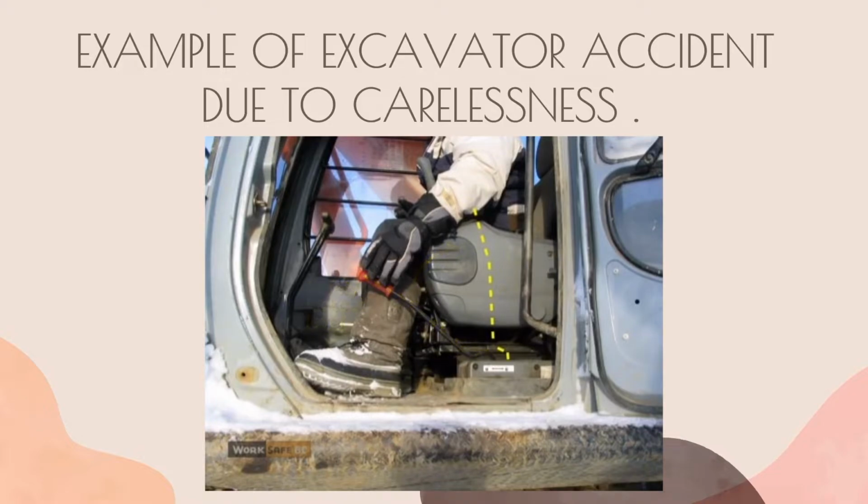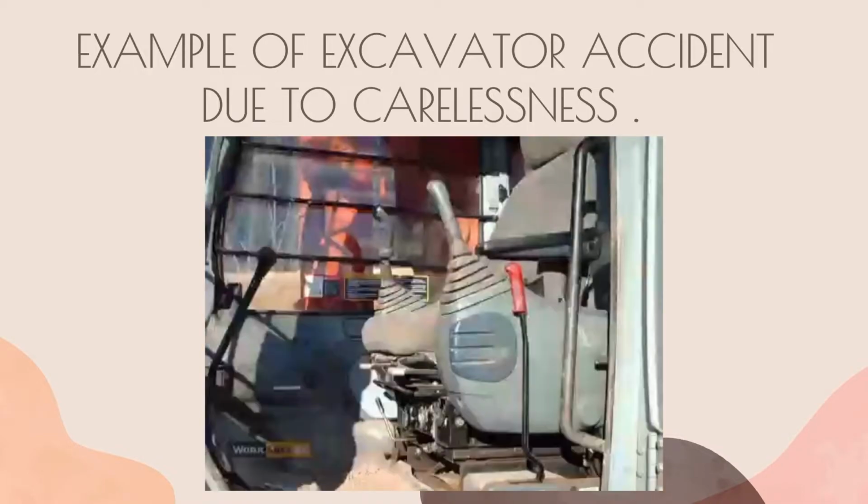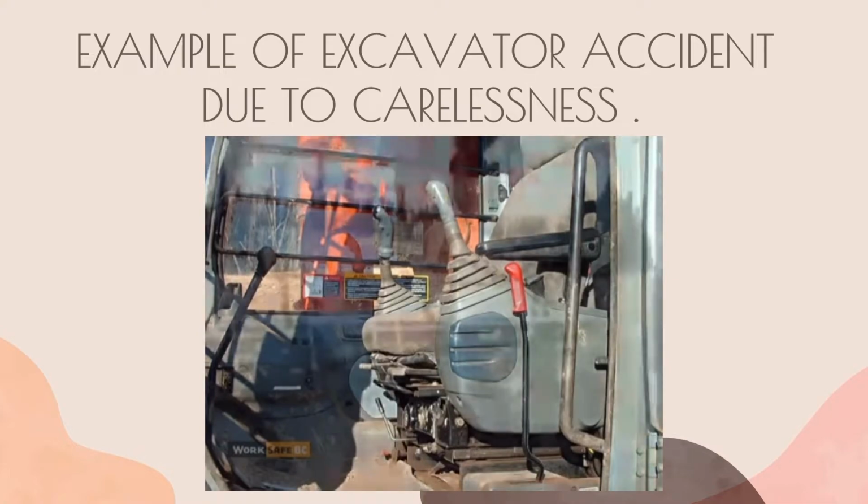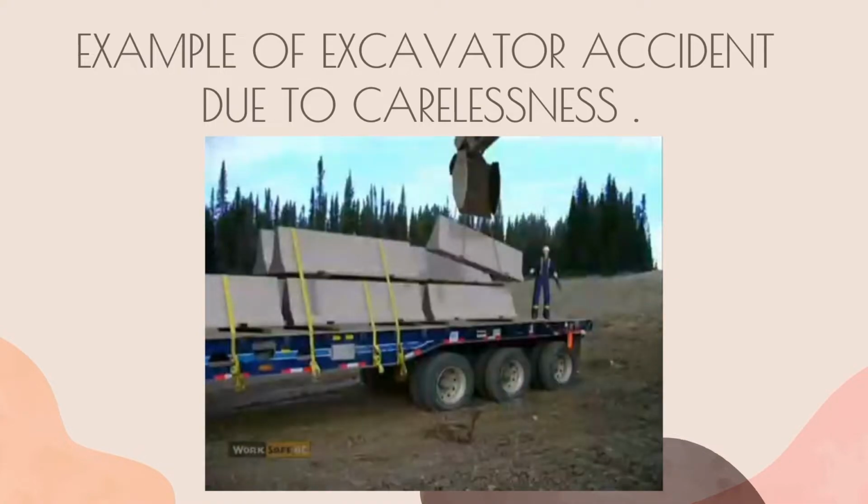He then exited his cab and talked to the driver. As the operator climbed back into the excavator, his pant leg snagged the safety lockout lever, releasing it. This enabled the controls. His left pocket then snagged a joystick. The excavator's boom suddenly swung.